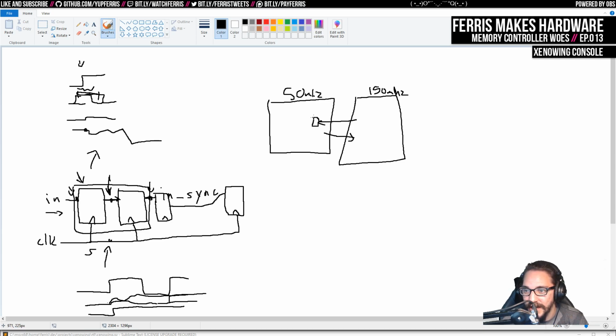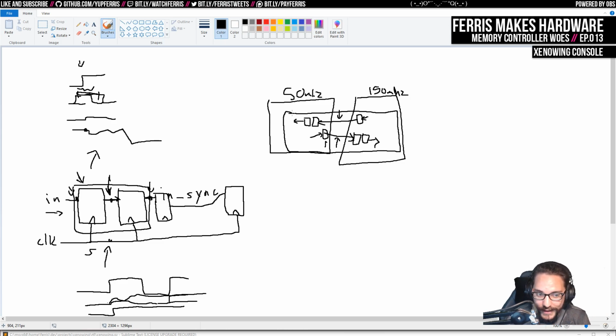So you need a synchronizer chain in here, and you'll need a synchronizer chain in here. And also typically to make this delay as long as possible, you also will do registers on the outputs of these. So you'll have some logic that outputs the value you want to send here, and then on the next clock, it will go here, and then 2 of these clocks later, it will actually get that signal. And the same thing here. So a bit of latency there. But again, if this is all in a FIFO, then you'll still get pretty good throughput through that FIFO, even though you have these few cycles of extra latency through that.